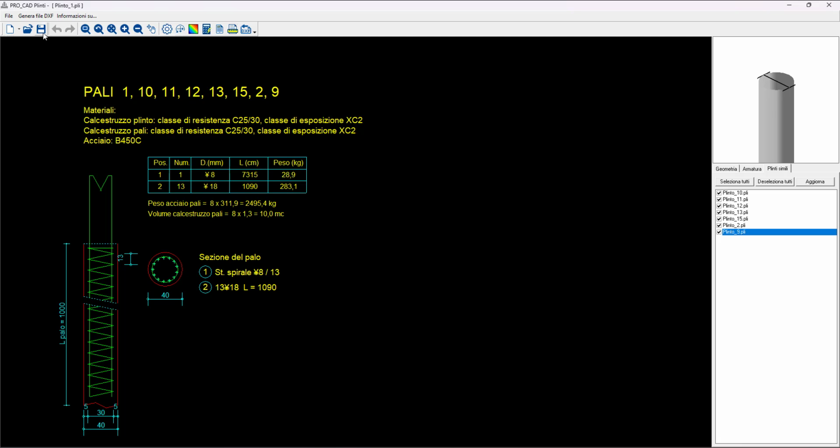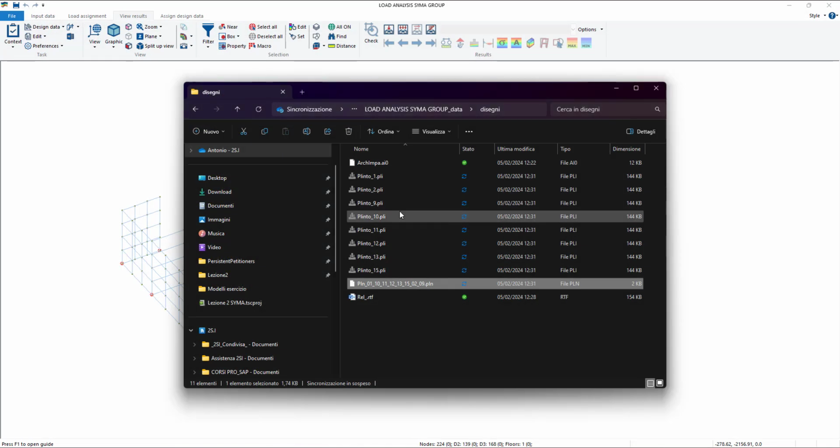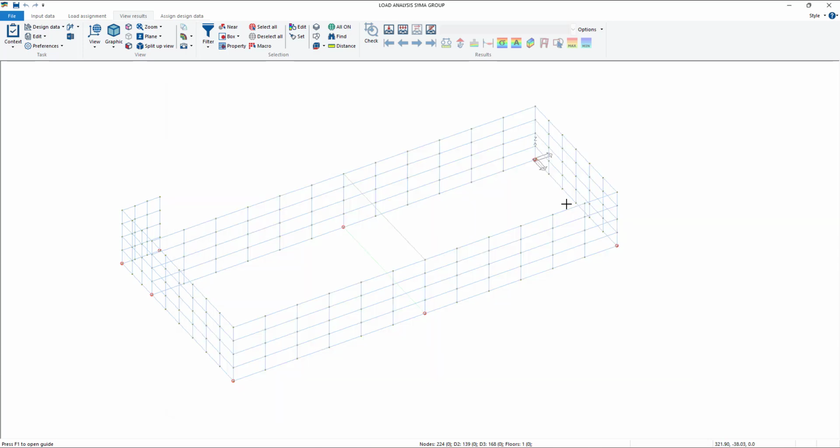Okay, so this was all for this block add plinth. You can save, you then go out. It asks you again to save before exit. Say yes. It's better to save twice than not to save. And okay, now that you have designed the rebars on the plinth, you can basically go back on the geotechnical module with the design data, geotechnical analysis.